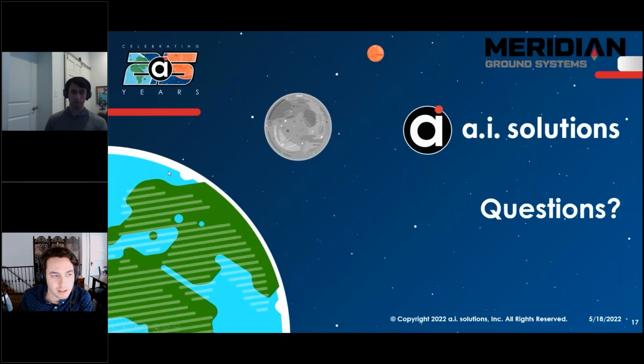Okay, cool. And following off of that, what probability of collision algorithm is used? Is it the same for LEO and for GEO? Yeah, so right now our CA tools are only recommended for LEO. For LEO, we're using FreeFlyer's built-in PC method, which is a 2D PC, and that's great for high relative velocity conjunctions. But at GEO, I think there's a lot more worry about low relative velocity conjunctions, where that algorithm starts to break down. So for a GEO mission, we would probably want to customize that CA tool a little bit to integrate any other PC algorithms.